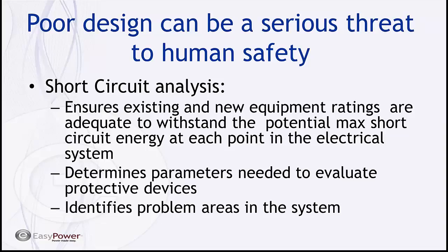Very frequently, because arc flash was not that well understood back at the turn of the century, pre-1998, a lot of buildings were designed inadvertently with arc flash hazards pretty much built into them, and it's not until we start to do arc flash studies that people realize how dangerous situations are and learn to either deal with them, mitigate the energy problems, or procedurally take care of situations that could potentially be harmful during normal operation.